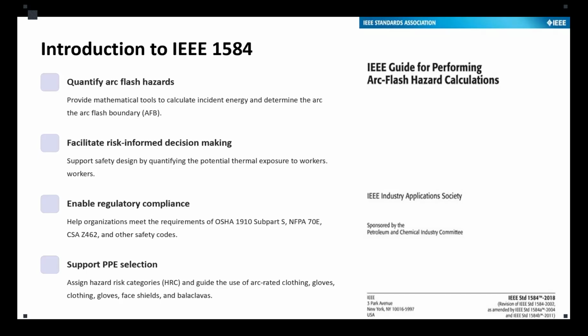This standard supports this concept by enabling engineers to model different scenarios and evaluate how factors like equipment configuration, fault current, and clearing time can impact workers' safety.